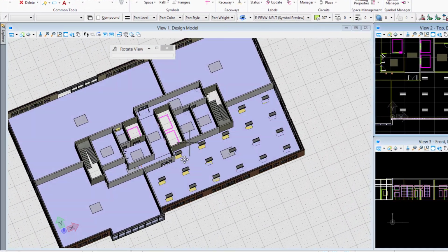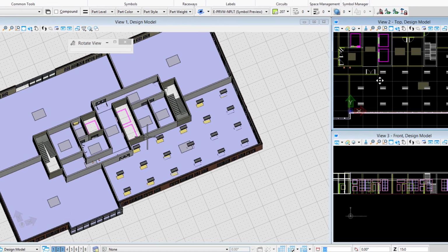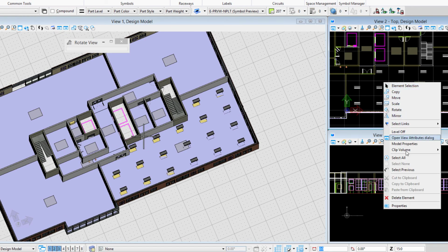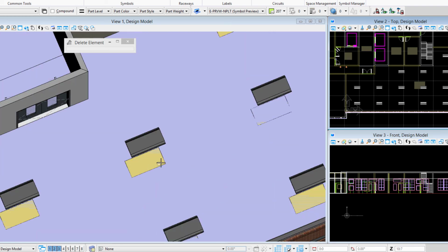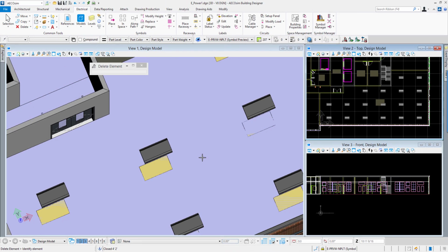Now you might need to clean it up a little bit. In fact, I'll come over here. Maybe I don't need a light fixture right here. And you can see how I have the 2D representation of the light fixtures at the 0 floor level and the 3D representation at the 10 feet height that I defined in the dialog box. So arranging lighting fixtures in a space without a ceiling grid.